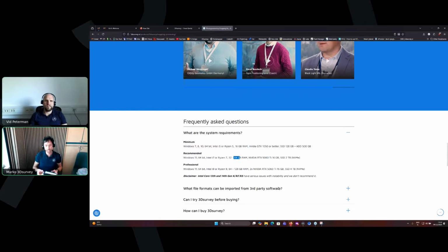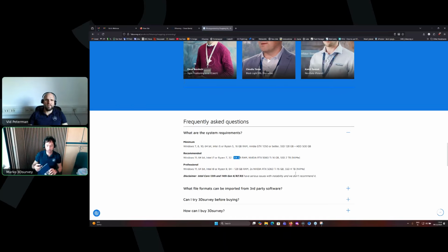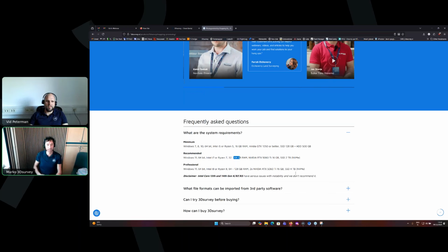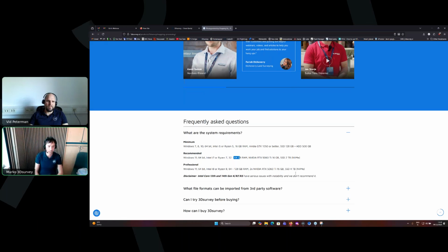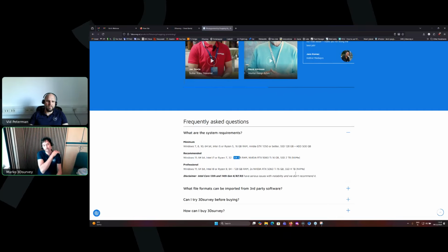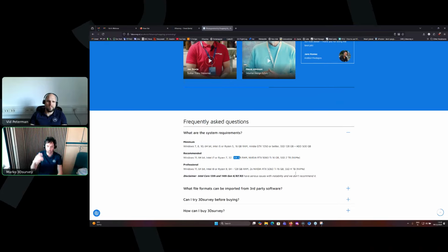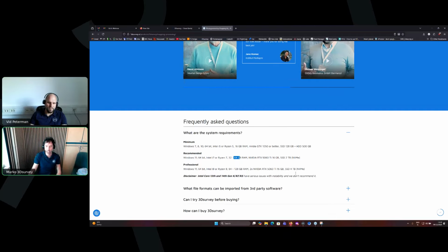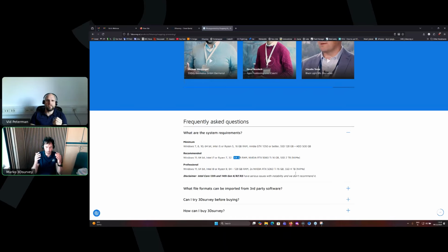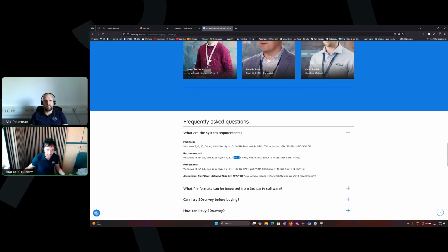So let's say the work starts on the field. Clever-wise, of course you can get the best and most powerful 3D model, but then it will take just 10 times longer. Depends what you need. And yes, think on a field not to produce too many images, because now DJI drones are capturing images like crazy in all directions, which is super good for nice 3D models. But depends if you like to be quick and you need just a volume calculation or just a standard orthophoto. You can achieve good enough results with 100 images instead of 1500 images.